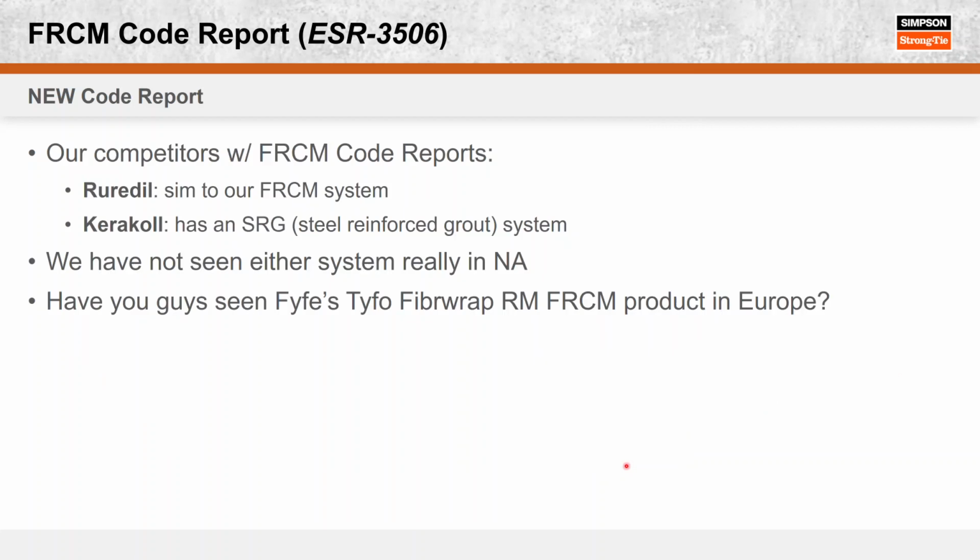And so our competitors that have FRCM code reports right now are two different companies. Ruredil is one of them. And they have a similar system to our FRCM system with a mortar and a grid. They have to hand trowel their mortar, so they can't shotcrete it. So they've got to mix it in a bucket and then throw it up on the wall and move it around with a trowel, where we can shotcrete ours.